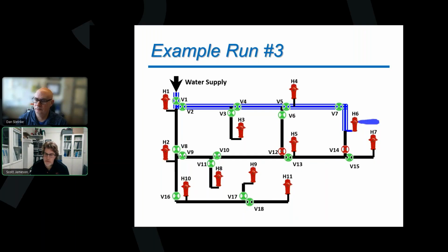The other thing I don't have on my map is elevations. So again, if you're flushing, look at the elevation change also, and pay attention to those high zones in your system, especially if you're flushing down at a low point in your system. The water is not going to want to go up into that high pressure zone or that high elevation in your system, so you're going to want to monitor those areas.